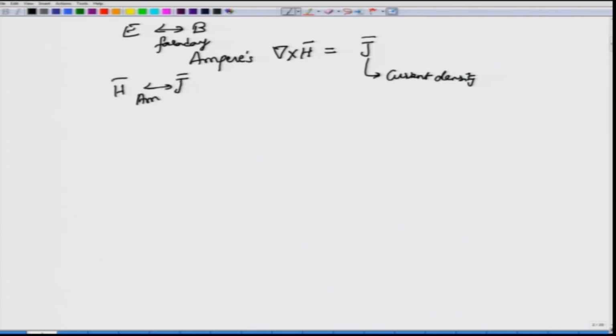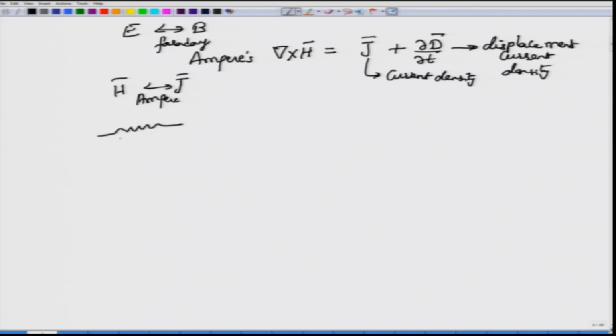So, this was Ampere, but what Maxwell observed after looking at these equations is that they are not consistent with what comes out from these relationships. So, he added a term to make it consistent and called that term the displacement current, or displacement current density. This kind of completes the current law. For example, you might have a regular conduction current density J, but when you connect a capacitor, clearly there are no free electrons inside this capacitor, right. So, how would current then continue?